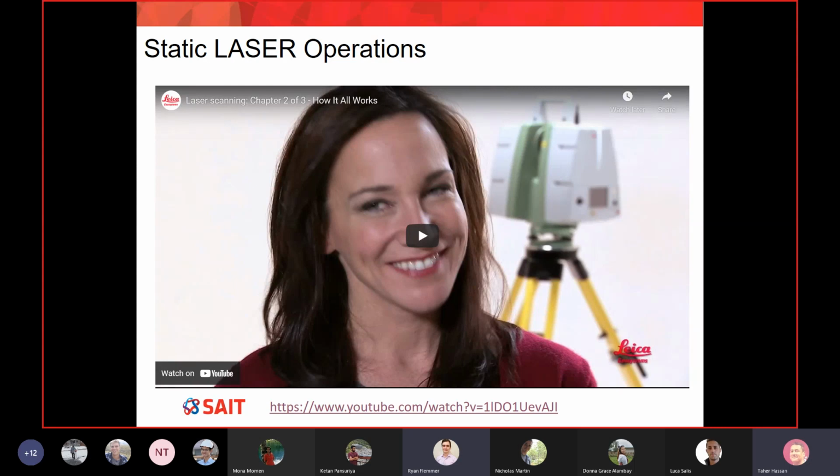Exactly. To my view, the laser scanner is a total station, so it has no more measurement than a horizontal direction with a vertical angle, with a slope distance to where you want to find the XYZ. The difference is the total station picks a very specific point where you need to place a target or a prism, or you can use the total station in reflectorless mode to find the XYZ, while the laser scanner probably has a stronger signal, so it works always in reflectorless mode. However, it simply continues the process continuously.